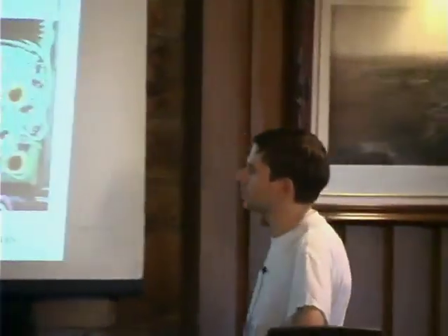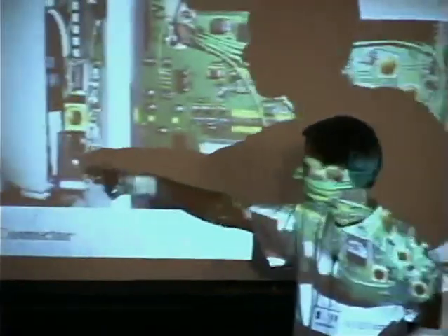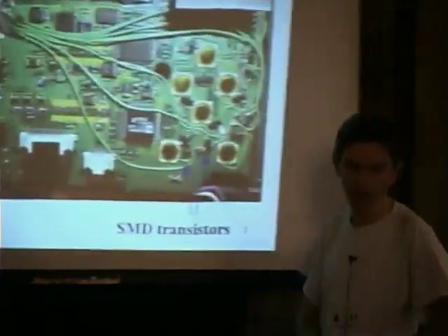And between the camera and the cradle, I use a bus protocol that is the I2C bus. That's a standard bus with only 2 wires. You can exchange data between 2 parts. The I2C bus is a bus you have in your digital camera, in your TV set. That's something very standard.